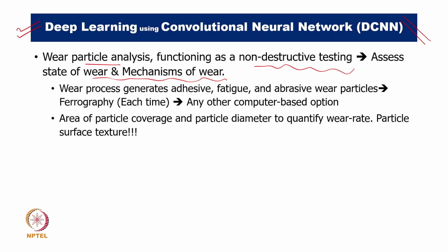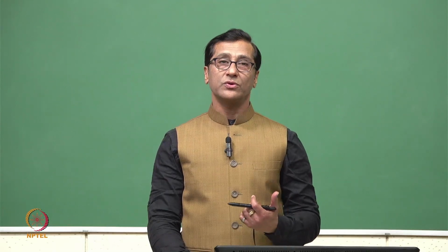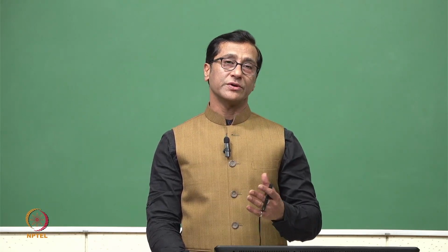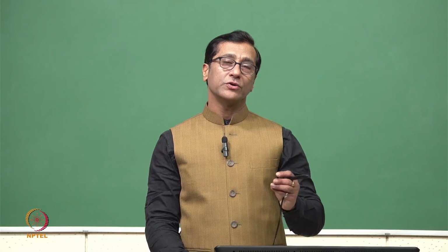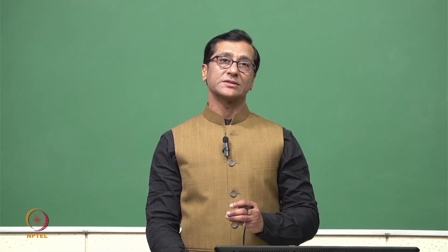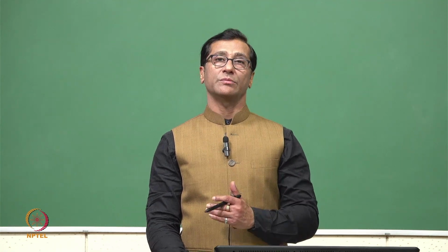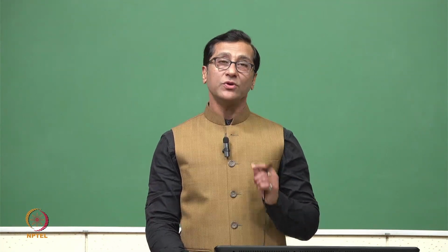Now here we require images. The classification is related to adhesive wear, fatigue wear, and abrasive wear. In this situation, earlier we were using ferrography. Every time you go ahead with particle analysis, we extract the oil sample, we filter it, we remove the oil using the ferrography equipment, and then go ahead with three to four levels of particle sizes, and then we use some sort of computer-based option to say whether it is a smaller particle, medium-sized particle, or bigger particle. But that was only experiments.